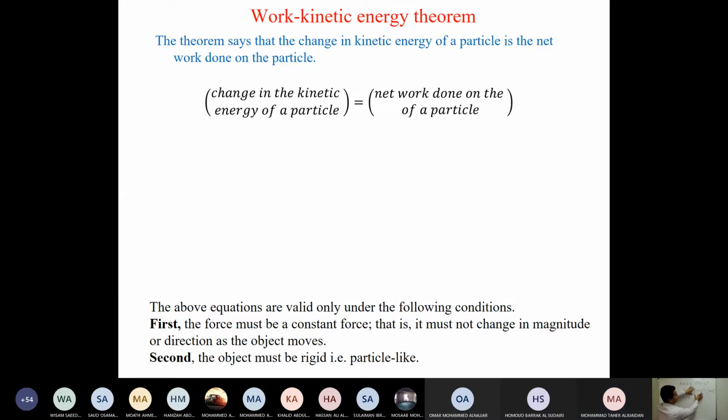And this equation is, half mv squared is kinetic energy. So this is the final kinetic energy, and this is the initial kinetic energy. So just from the equation of motion, we can tell that if a change in the kinetic energy is happening, that will be due to the work, right? Either the work is done on the system or by the system. So you can see either the initial kinetic energy will be more or the final kinetic energy will be more. And accordingly, the sign of the work will become positive or negative. So this is the work energy principle. It comes from the equation of motion.